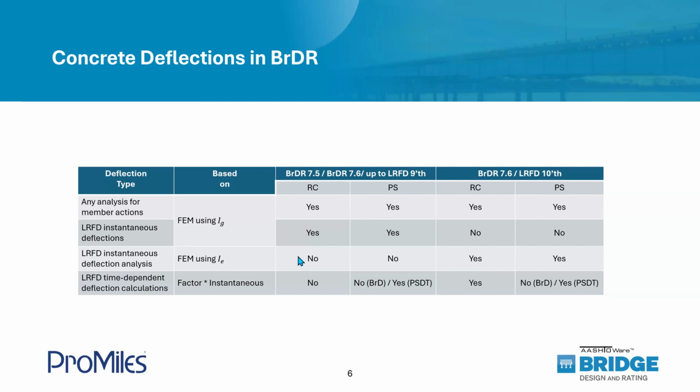We also did not have the time-dependent deflections for RC. We did not have them for PS either, at least not in BrDR. We did have them for the prestressed design tool, PSDT, but they were calculated based on PCI multipliers, not the formulas from LRFD. So we still don't have